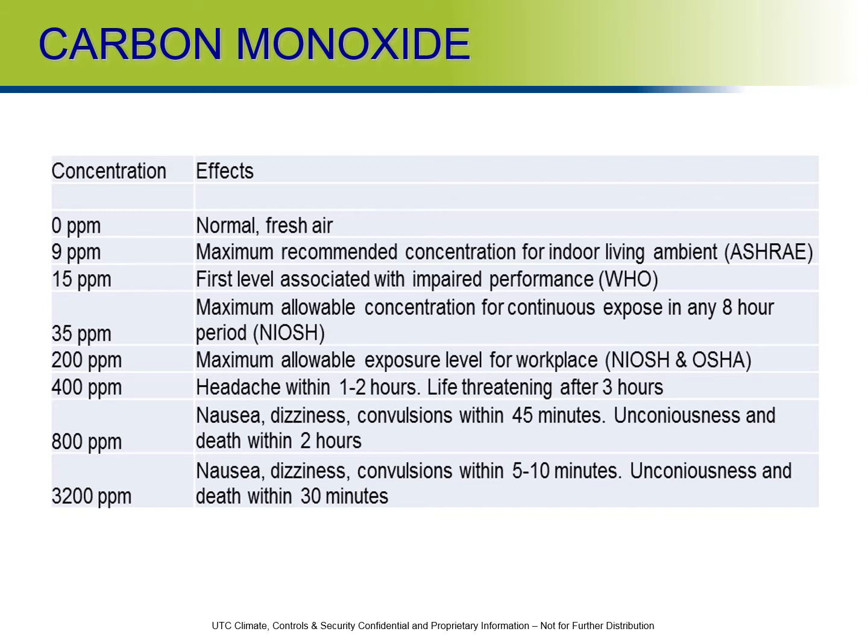Okay, so at 35 parts per million, you could be exposed to that for 8 hours a day and be okay. It's not going to have a harmful effect on the body. All right, so 200 parts per million is the maximum allowable exposure level for a workplace.